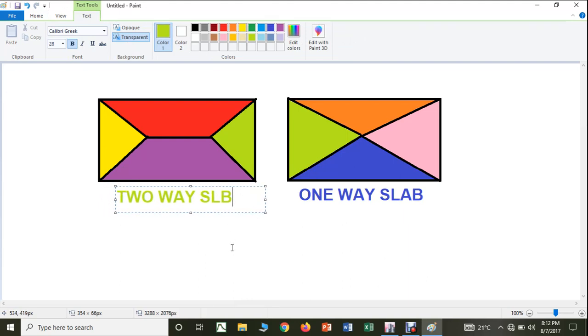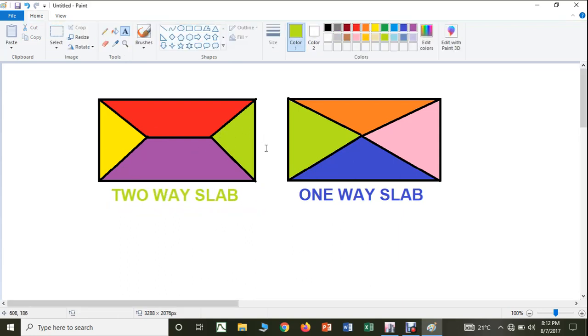So when you are designing manually, you have to calculate the load on the beam in this manner. But when it comes to ETABS software, learners, the software will automatically convert the floor load that you apply on the slab in this manner, and the beam will be designed.